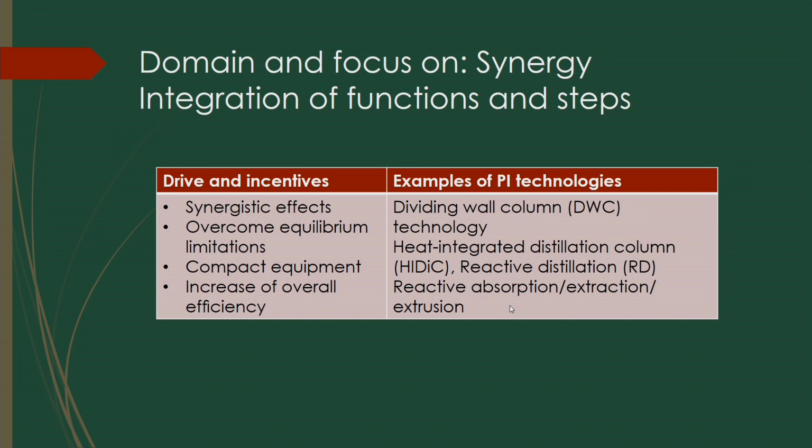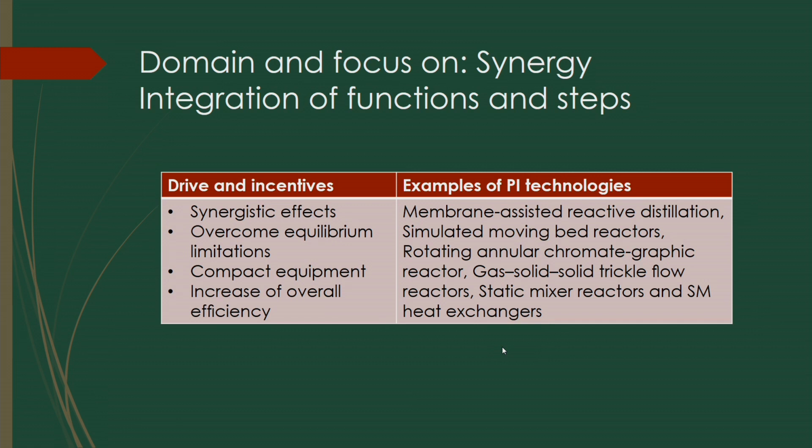Dividing wall column technology is also important. Heat integrated distillation columns are being used nowadays. Reactive distillation is used because conventionally only one simple operation was done in distillation, but nowadays this is not the case. In an integrated way, reaction as well as distillation happen in parallel in a single reactor, so it is called reactive distillation. Reactive absorption and extraction will also occur simultaneously in a particular reactor. Even in membrane assisted reactive distillation, sometimes after reactions you have to separate the products, so you have to use some membrane. So membrane assisted reactive distillation is a conjugated, or integrated, unit where this process intensification is done.